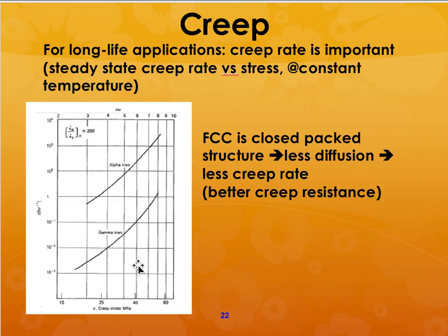Okay, and one thing to note is that FCC is a close pack structure, so you have less diffusion, which means you have less creep rate and better creep resistance. So FCC type of materials have better creep resistance than BCC type of materials.